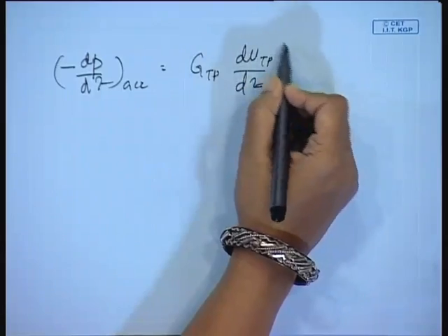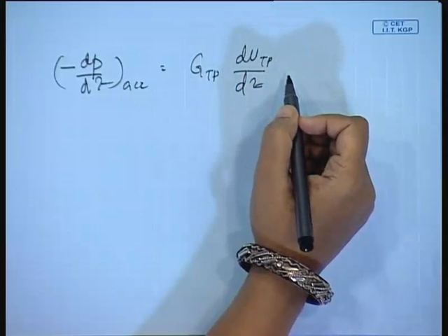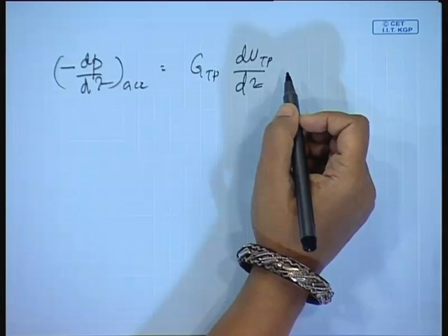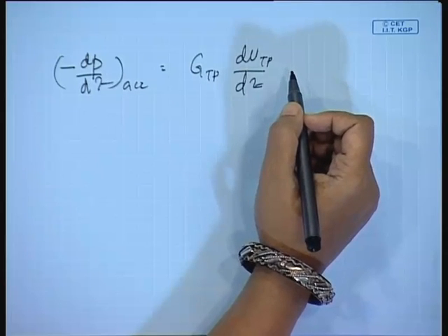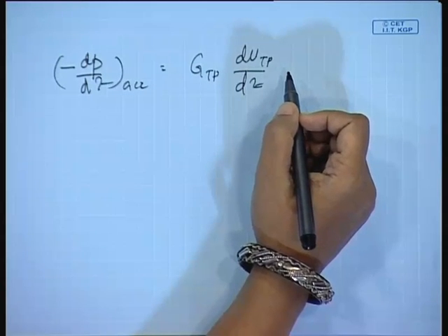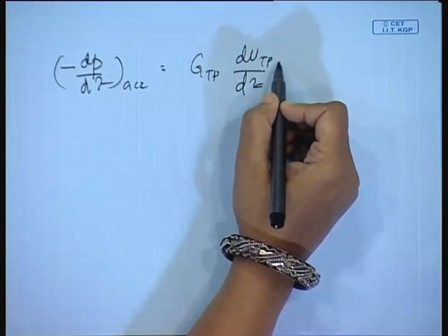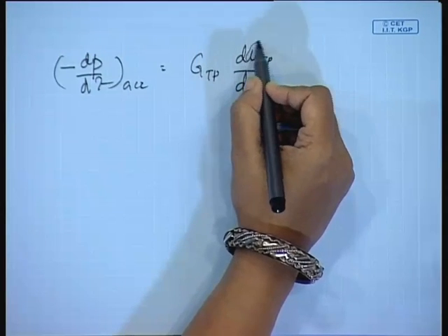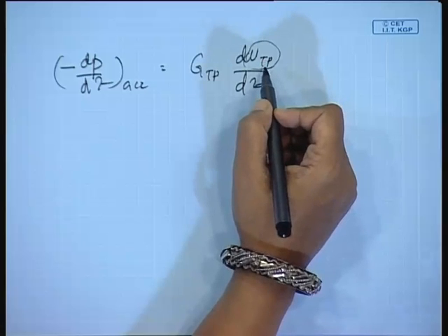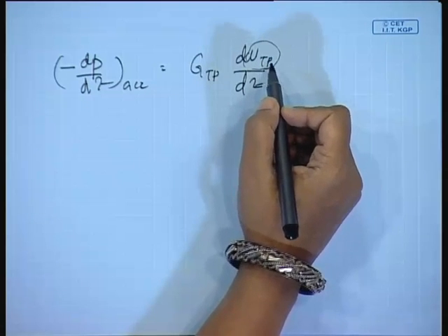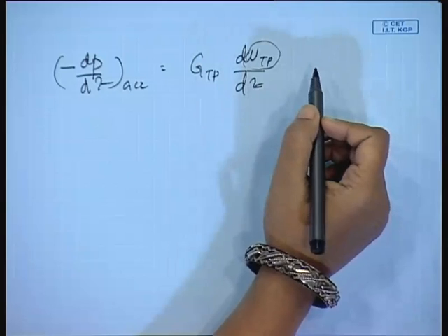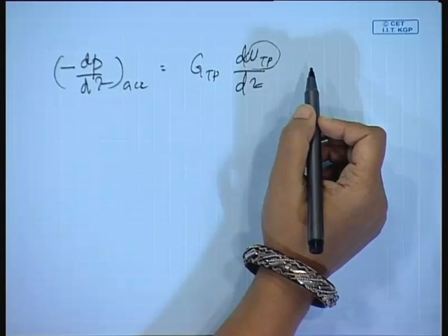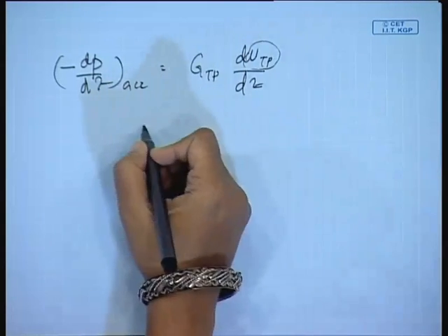Agreed? So, this acceleration pressure gradient arises just because one of the phases is compressible, or in other words, considering the compressibility of the phases. And there is one more thing, if there is an area change. So, in order to evaluate dP_acc/dz, what do we have to do? We have to express it in terms of those quantities which will be affected with axial distance, or which will contribute to the acceleration pressure drop. So, how can we express it?